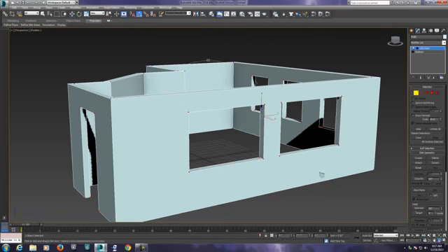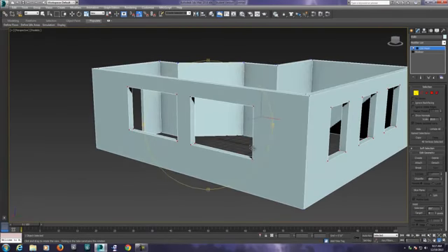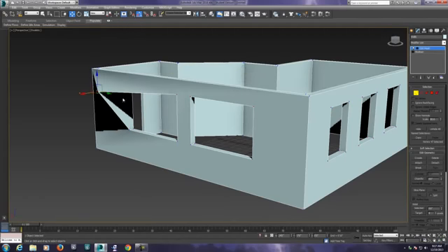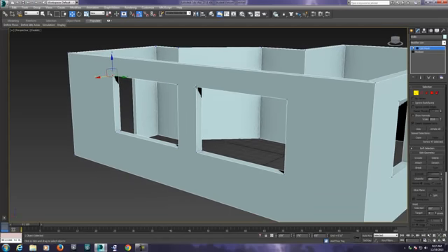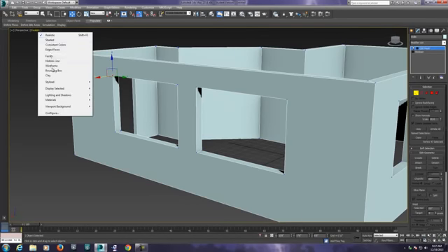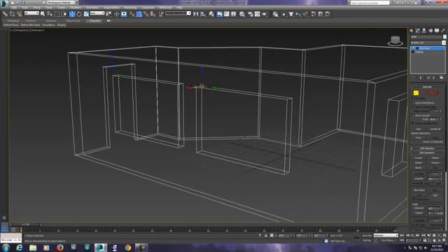Now just remember, when you resize something, that we have a thickness here. So if you just click one vertex and you move that vertex, you're actually screwing up the walls. If you want to move an entire window, you have to get the vertex here, and the one that's hidden back here. And if I go into wireframe, you'll see that there are these, and that's a common mistake that people have, is in one view they just click and they pull, and then they don't realize why the whole segment doesn't go.